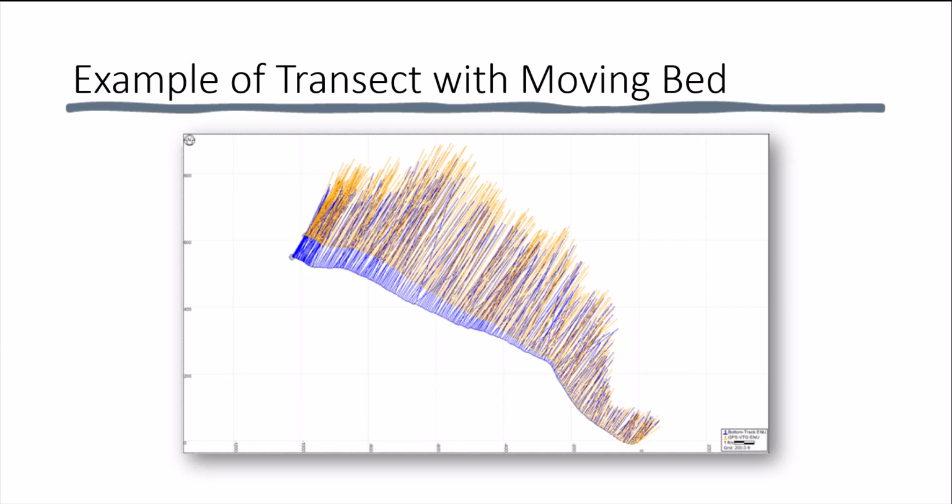However, when analyzing these types of plots, it is critical that the compass was properly calibrated, that the magnetic variation is properly set, and that there are no sources of compass error that may change as the boat moves through the section, or the difference between the bottom track and the GPS could be compass related and not due to a moving bed.